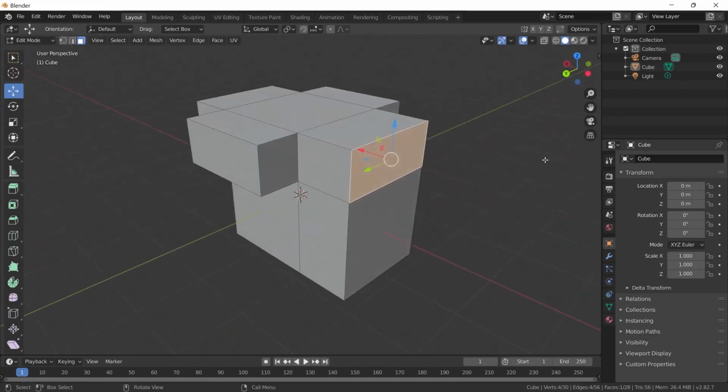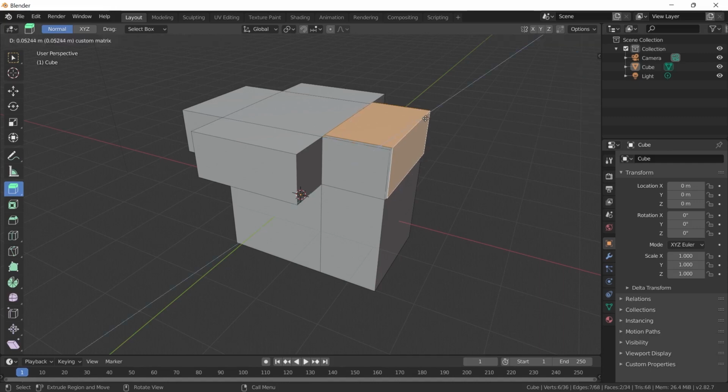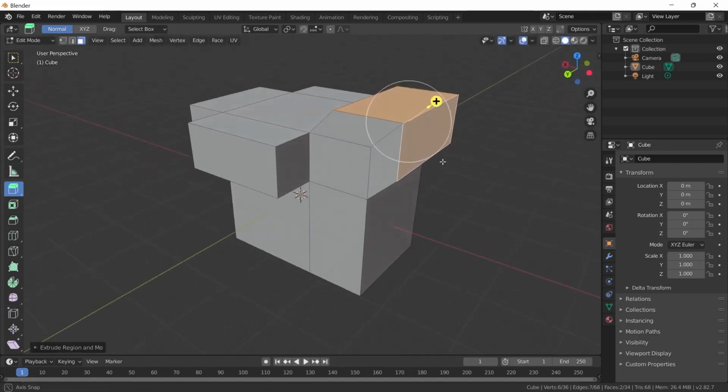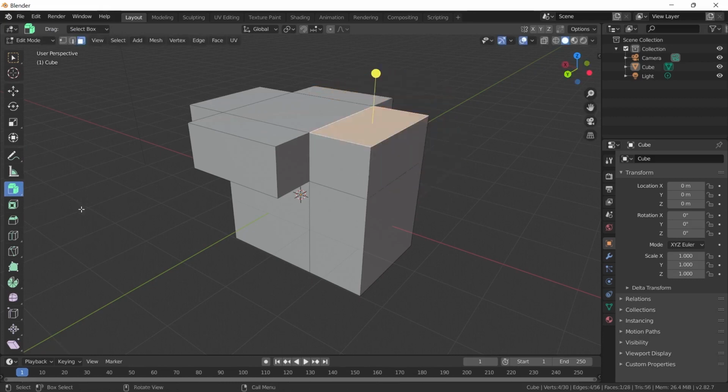Again, there is another extrude option that we need to know among the extrude options. I will show it as follows. I will see what a normal extrude operation means. I press the letter E on the keyboard. I perform the extrude operation as standard. You see the operation. This is how it made an extrude. Now let's do this extrude individually. When I do extrude as an individual, it completes this extrude process towards their own paths, towards the direction where their own faces point.